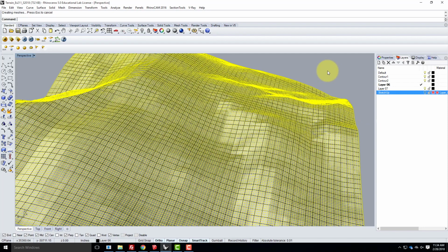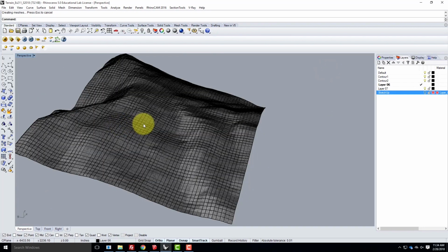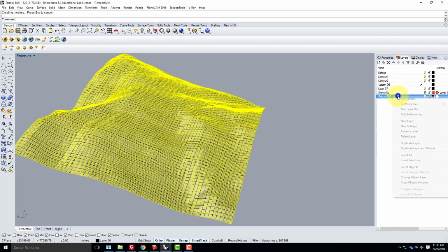So when I do these rebuilds, I'm going to show you in contrast to the SketchUp surface. I'm going to create separate layers for each of these rebuilds so that I can toggle between them. In all likelihood, you're going to do one and call it a day. So I'm going to have more layers than you, essentially. So I'm going to start. This is my rebuild at 200. Let me take the resulting surface there, and I'm going to change the object onto that layer.